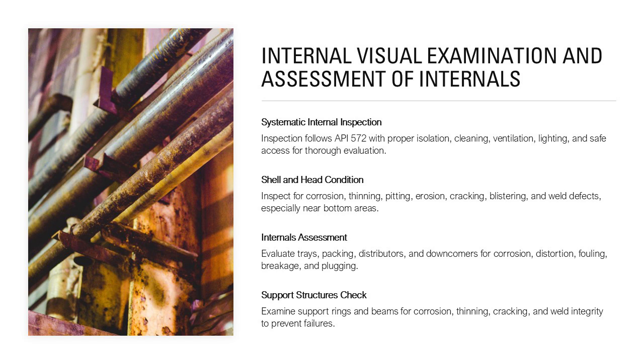Support rings and beams are critical structural components and must be thoroughly examined for corrosion, thinning, and cracking at welds. Failure of these components can lead to catastrophic internal collapse. All findings should be photographed, measured where applicable, and compared with previous inspections to assess deterioration rates.